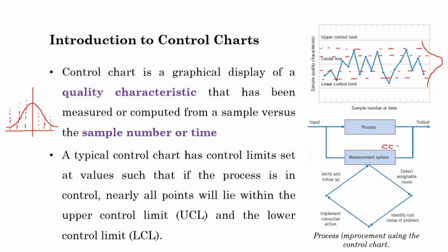So when you use the control chart and identify that there is a point, for example, here, let's say the next point is out here, then it is telling you that you need to initiate an out of control corrective action. So you initiate this out of control corrective action plan in order to detect the assignable cause.